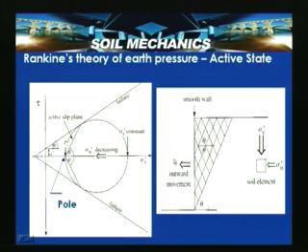Now, once again let us look into this. This is the active state Mohr circle tau sigma plot which is shown here, and this is sigma v, the vertical stress which we know. From the Mohr circle fundamentals which you have studied in shear strength, from the known state of stress on a Mohr circle, when you extend a line to the other part of the Mohr circle, we can locate that point as a pole.